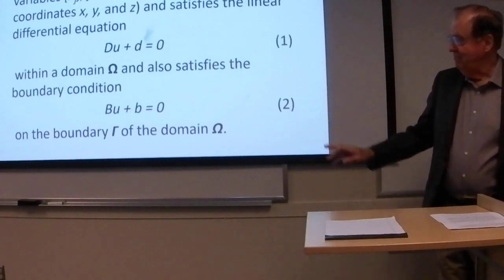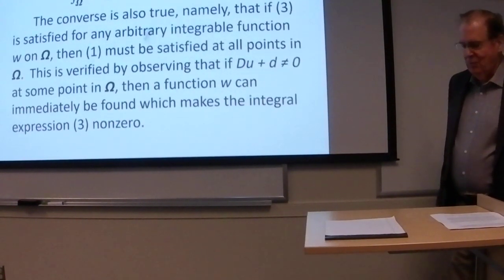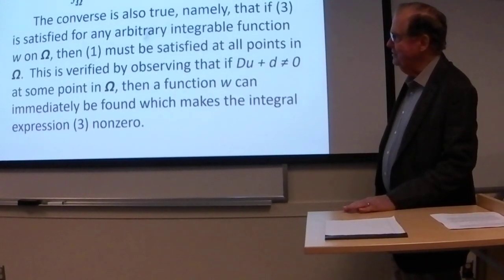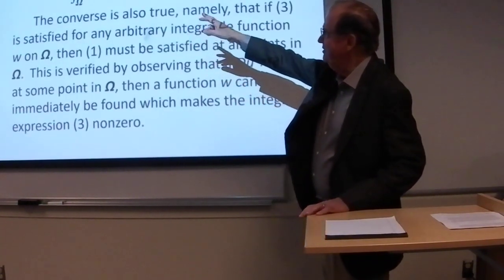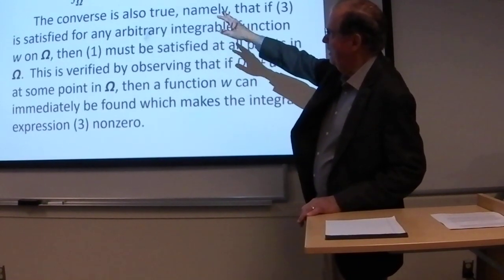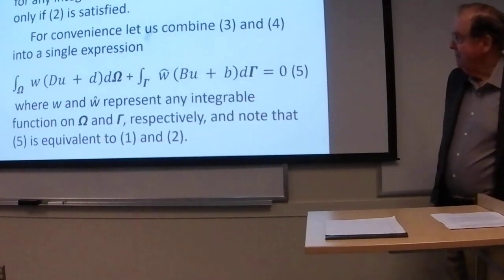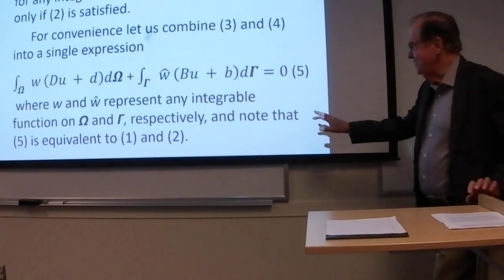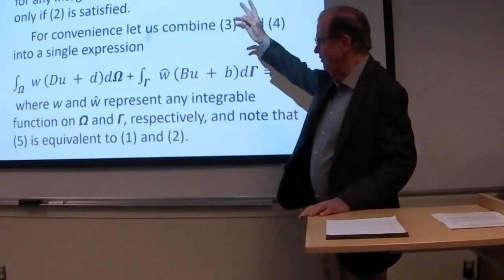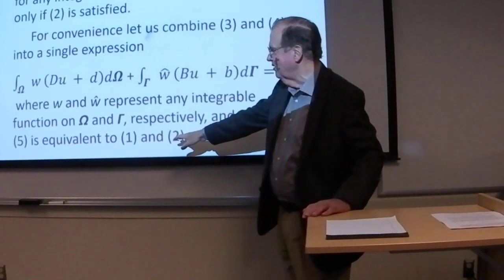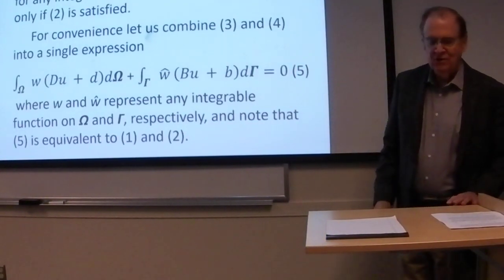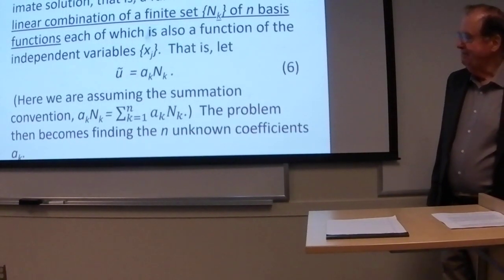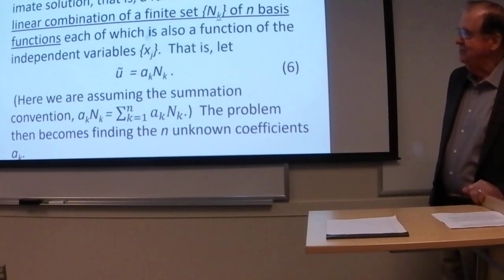this Galerkin method is doing the same thing as the finite element method does, and we showed that this Galerkin method utilizes what are called test functions, the integral of a test function times the basic equation. So it expresses the original equation in what is known as weak form. This weak form that we see here is equivalent to those equations 1 and 2, which are often referred to as the strong form of the equations. But the weak form and strong form are equivalent, and as I tried to say at the end of the last lecture, there are some computational advantages to the weak form.